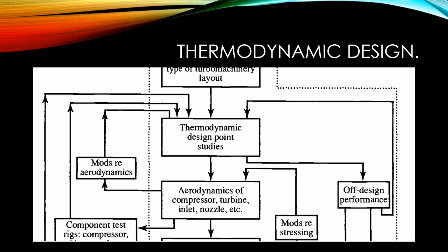In industry, these calculations will be carried out using sophisticated software, but we must understand that there is no mathematically defined optimum. For example, at a specified turbine inlet temperature, a large increase in pressure ratio may give a minimal improvement in specific fuel consumption, and the resulting engine would be too complex and expensive to be practical. Other considerations, such as mechanical and aerodynamic design, must be taken into account in this stage.